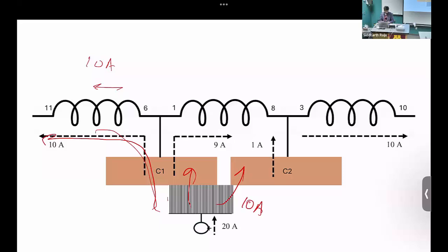Okay. So how it splits is a very complex way, a complex equation that will come out of it. But in our case for now, let's just look at it theoretically, that it's going to be proportional to the resistance of the brush versus the commutator segment that we are connected to. So right now, say 10% is making contact with the second commutator, 90% is making contact with the first commutator. So the current split would be 10 there, 90 here. All right, just looking at it as if it's purely resistive. So this current at this coil is now going to start to drop. So previously it was at 10 ampere. This current is going to start to drop. It's going to go to 9 ampere while 1 ampere starts to go out of this branch.